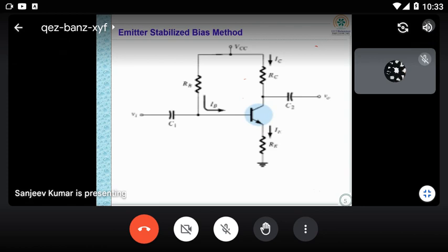And you have seen earlier, because no resistor is there, all the current flows to the ground. That is the design point of view. Whenever you calculate the stability, it is lesser in the case of the earlier method. So to improve that, and I'm repeating many times, only one additional resistor is connected across the emitter.